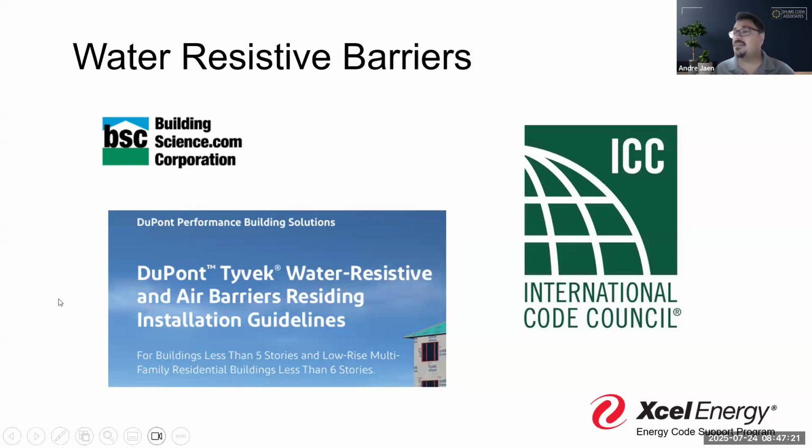Also, never discount, obviously, your manufacturer installation instructions, right? Those are a key resource and place to go to. So I have, for instance, DuPont's Tyvek water resistive barriers guide, right? And you notice there it also says air barriers because it can be used as an air barrier. And this is one of those places where setting the expectations for your inspection process to say, have those on site, especially if you want to use it in this format, really will pay dividends as you get better plans for discussing this issue of getting better air barriers.